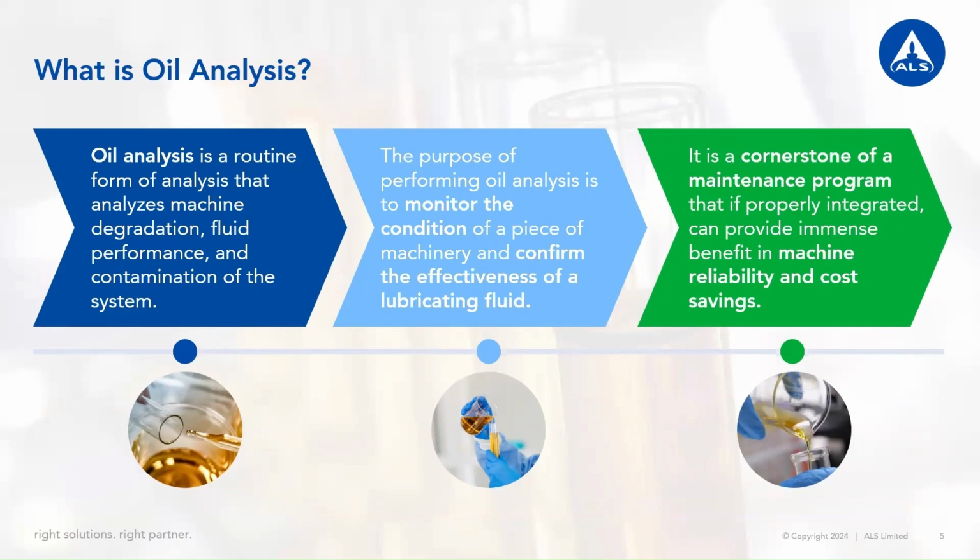In order to reach the goal of these predictive and proactive maintenance strategies, a business will need insight into the internal workings of their equipment. This is where oil analysis comes in. Oil analysis is simply the routine monitoring of equipment health, fluid performance, and contamination control. By monitoring these areas, maintenance departments can make repairs, part orders, fluid changes, and process improvements without major impacts to the daily operation of the business. Maintenance can be planned in advance, and actions can be taken to minimize common pitfalls of unexpected issues.